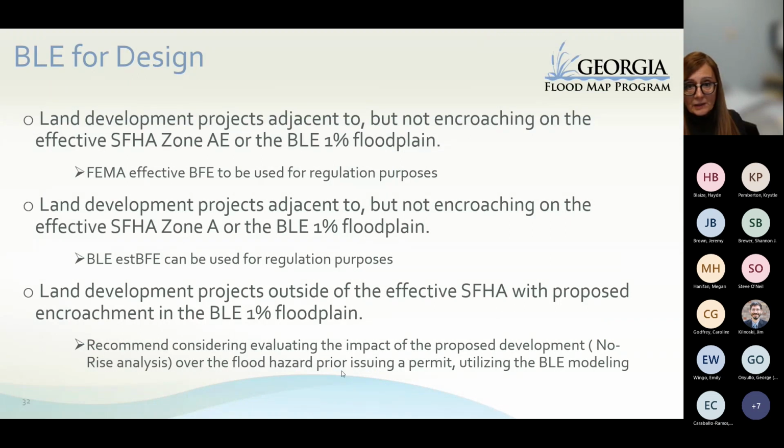Here in the next two slides, I'm going to cover several examples with the proposed developments when they're adjacent or encroaching in an effective special flood hazard area or in the base level engineering floodplain. So the first scenario is if you have a proposed land development which is adjacent but not encroaching on the effective special flood hazard area zone AE or on the 1% base level engineering floodplain.